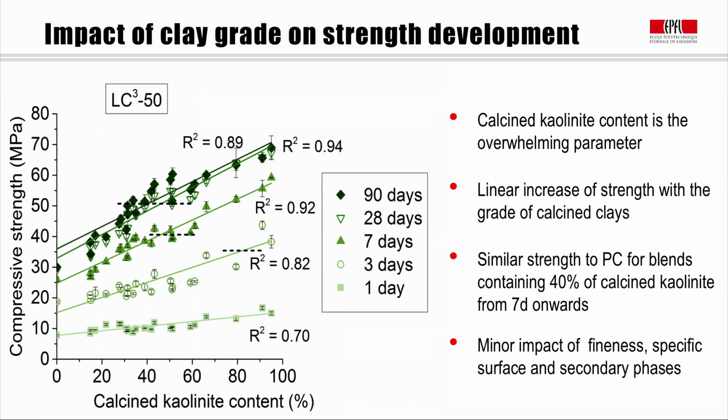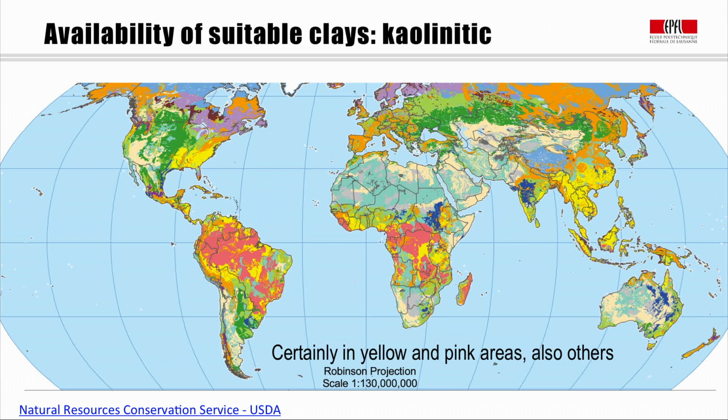High purity clays, notably used to produce metakaolin, have very strong requirements for color, for purity, etc., which makes them very expensive. Whereas these kinds of clays, which contain much lower amounts of kaolinite, only say 40–50%, are generally waste materials, which are consequently much cheaper.